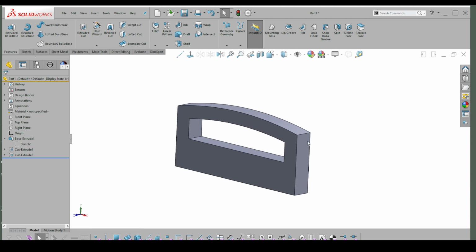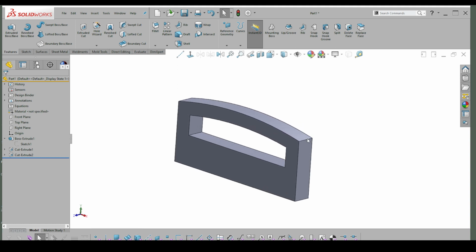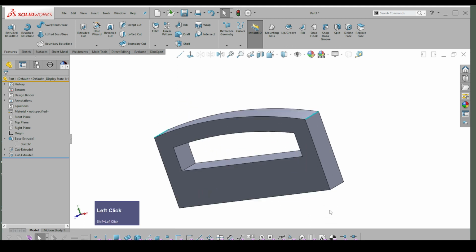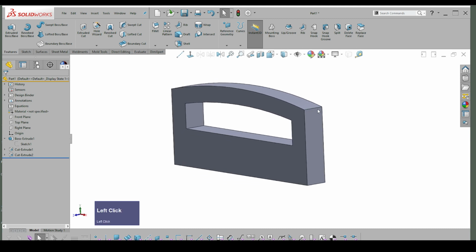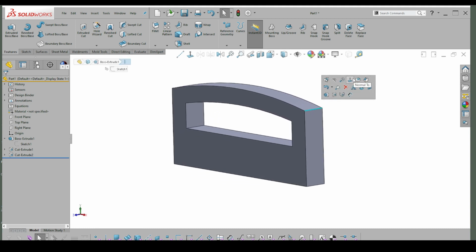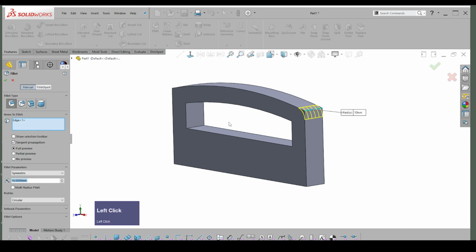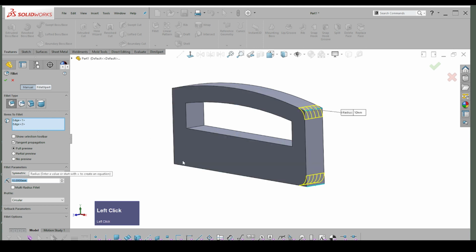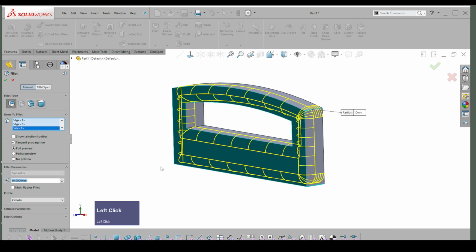And from this point, I could put in the fillets, the large fillets. So if you put fillets in, you go from largest to smallest. So if I click on one fillet and I use the fillet command, then I can in fact choose the other fillets. It's hitting a face. I can choose the other fillets. I should be able to choose them. No.